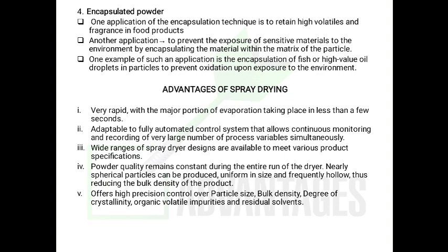Here are some advantages of spray drying. The process is very rapid, with the major portion of evaporation taking place in less than a few seconds. Adaptable to fully automated control system that allows continuous monitoring and recording of very large numbers of process variables simultaneously. Wide ranges of spray dryer designs are available to meet various product specifications. Powder quality remains constant during the entire run of the dryer.